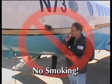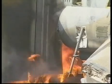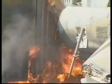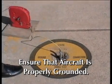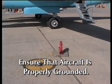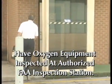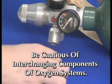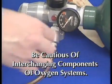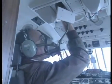Do not allow anyone to smoke around oxygen equipment that is being used or when maintenance is being performed. Oxygen supports and rapidly accelerates the combustion of all flammable material. Ensure that the aircraft is properly grounded before loading oxygen. Make sure your oxygen equipment is inspected regularly at an authorized FAA inspection station. Be cautious of interchanging components of oxygen systems. Ensure that all components, storage, regulators, and masks are compatible.